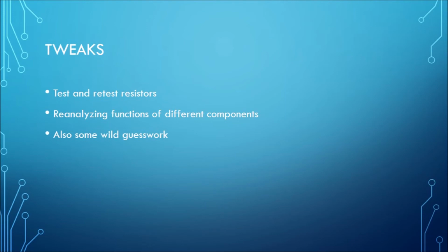So in practice, this meant going through most of the resistors, looking at what they're for, and trying to adjust their values higher, lower, seeing what was happening, and using that to confirm or deny what we thought the circuit was doing compared to what it was expected to do based on our simulation and calculation.